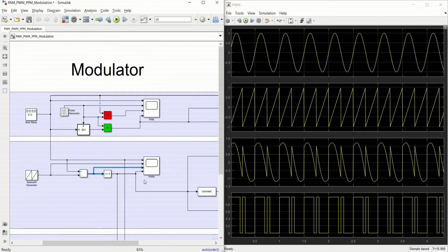And lastly, on the third waveform we use a comparator. So any value which is above 0 is considered as 1, and any value which is less than 0 is considered as 0. Hence in the fourth waveform, which is the output of this comparator, we have a PWM signal. Note that within this duration, that is 0.5, we have two pulses of PWM, and each pulse takes a fraction of the duration of 0.25. So this fourth waveform is our PWM signal.